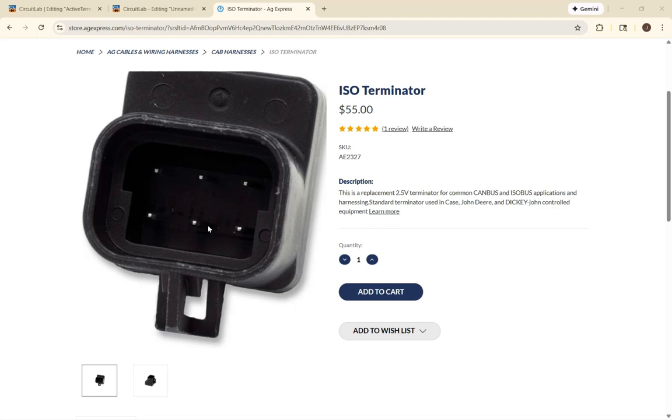I know that John Deere techs refer to one of them as the active terminator and the passive terminator. As an electrical engineer, that's really tough for me to use that terminology, but I'll try to stick with it for this video, even though I may not agree with the terminology. In recent times, most manufacturers, I think, have gone away from active termination and are using just passive termination, with the exception perhaps of the implements and the implement bus on some machines.